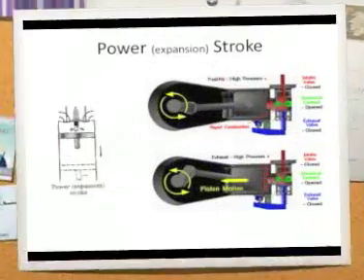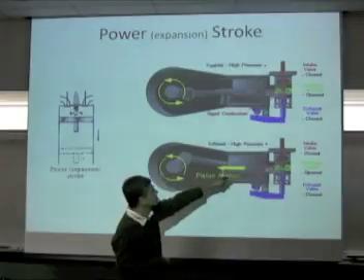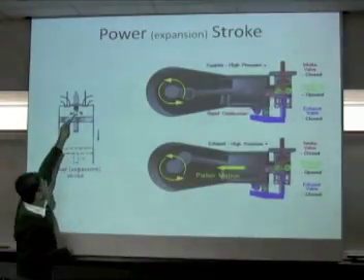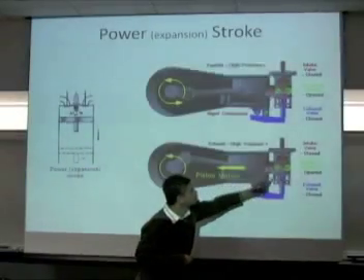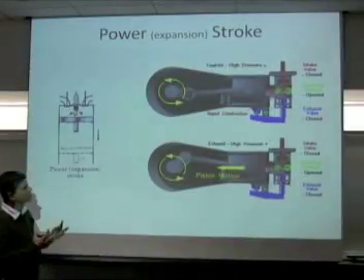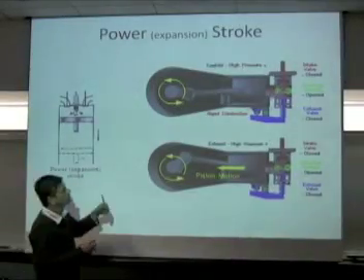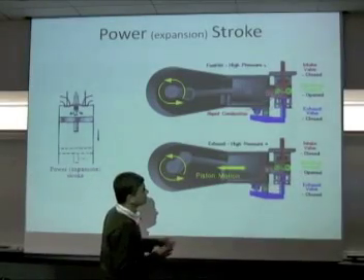Then we move on to the next part of the cycle, where this high pressure air comes in contact with what is called the spark plug right here. The spark plug is ignited, and this air-fuel mixture combusts and produces high energy. It's called rapid combustion because it goes very fast, within a few milliseconds.